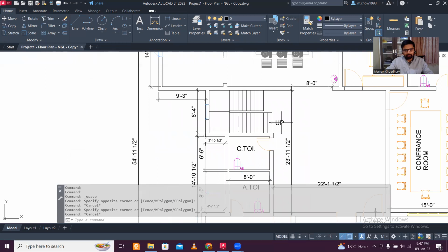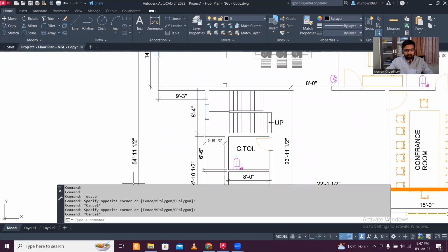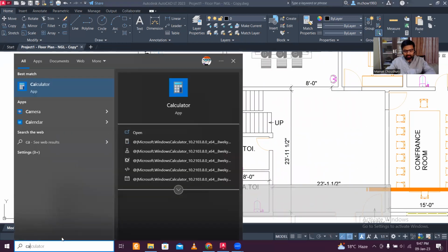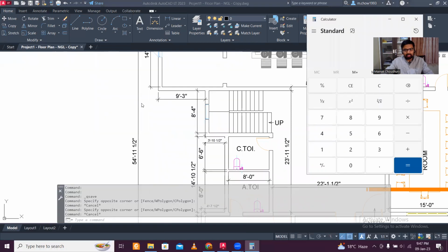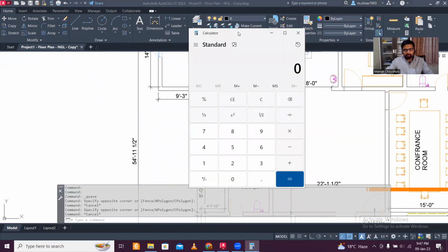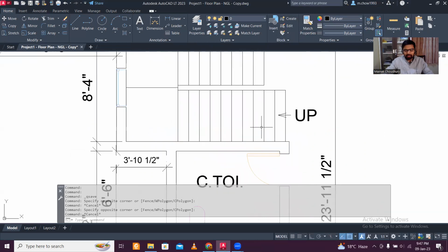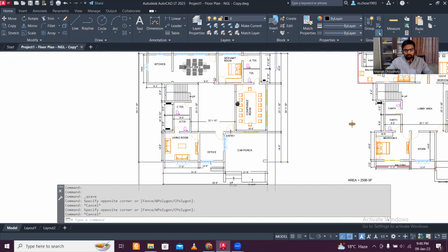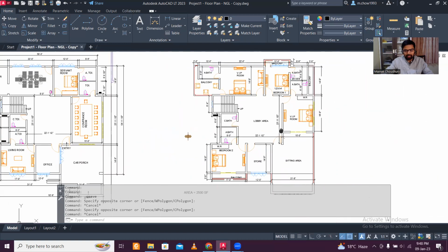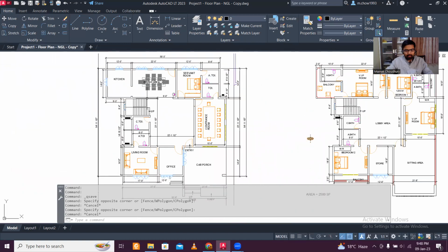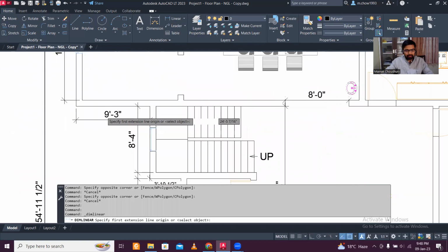So if you are taking 6 inches, or rather in mm, 150 mm. So 20 into 0.15 is equal to 3 meters. So 3 meters is the floor to floor height here, given that they have taken standard risers. So we're going to go with 3 meters here. No problem in that. And let's look at the wall widths here.